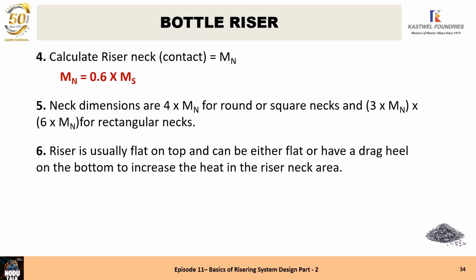After you get the riser significant modulus, you get the neck modulus. After you get the neck modulus, you know how to design the neck, round, square, or rectangular necks. 3 times the modulus gives you the height of the neck, and 6 times the modulus gives you the width of the neck.